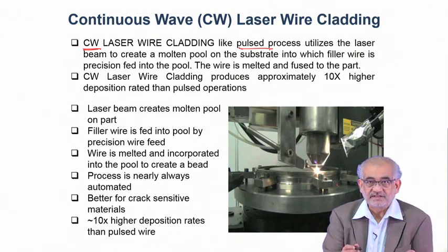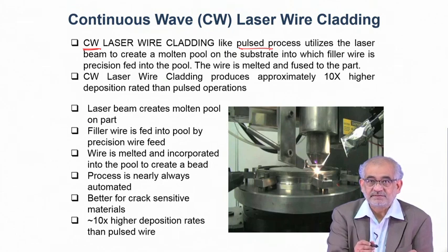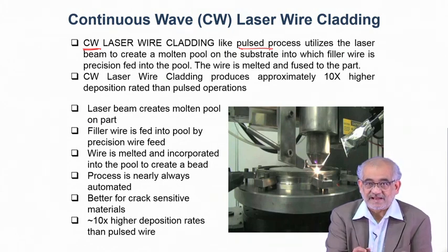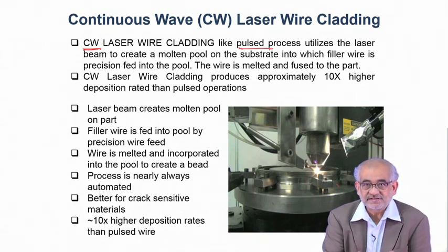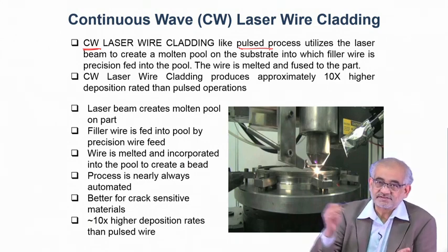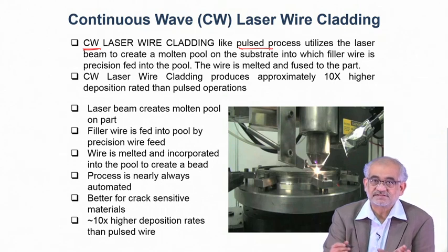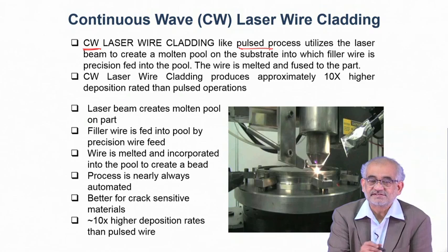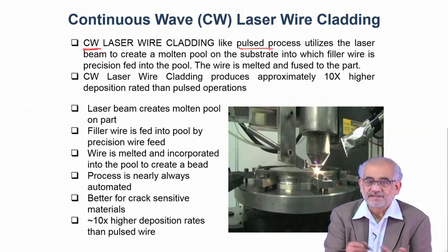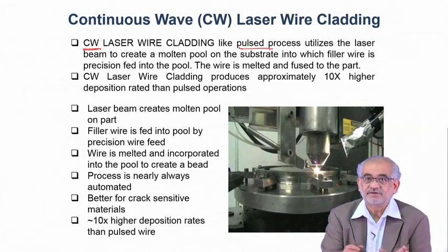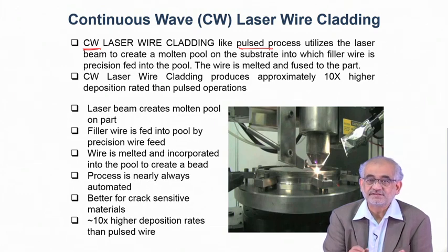So whatever you melt and overlay, if it's pulsed mode, then you create a splat, a transient, momentarily melted pool. And when it starts solidifying, it creates a solid crust on top of that. Now the next splat comes in a molten form, and has to first weld with this semi-solid form. That unnecessarily wastes some amount of energy and moreover creates certain non-uniformity, which we don't want.